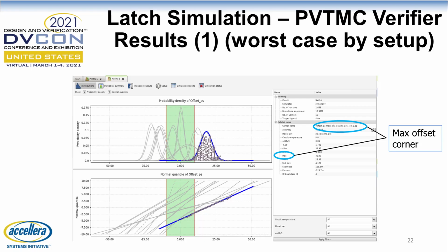However, we are looking to find the widest distribution and not the one that is to the far right or the far left. If the distribution is narrow, it can be digitally corrected. If it is wide and washed out, then we have to investigate further, and it is a red flag for us. The wider the distribution, the higher the number of bubbles we get in the thermometer code, and the lower the performance of the ADC.